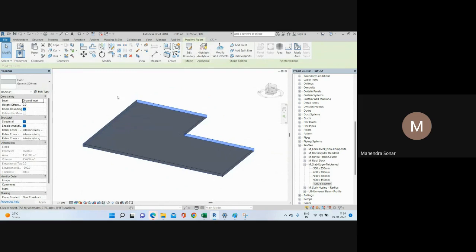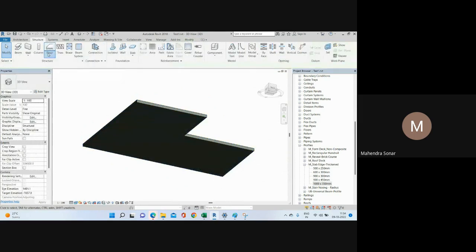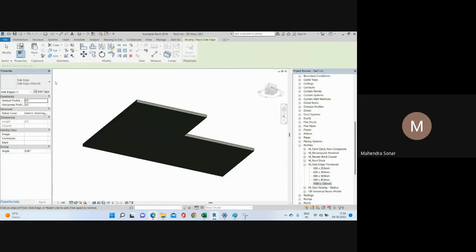Then after that you need to go floor category and use this slab edge. Select this and then move your cursor any edge of the slab, here, here, or here. Once you move your cursor, so this edge is highlighted. But I don't want to click each and every edge. Okay, so move your cursor and press the tab button. So it selects all the perimeter. You can see all perimeters shown in a blue line, right?